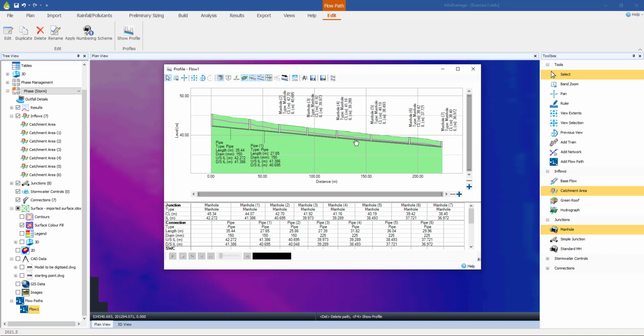And that's because we could only lay them at a certain slope to meet either the slope criteria that we specified or the velocity criteria that we specified. So because of that, it's laid at a particular slope. Okay.